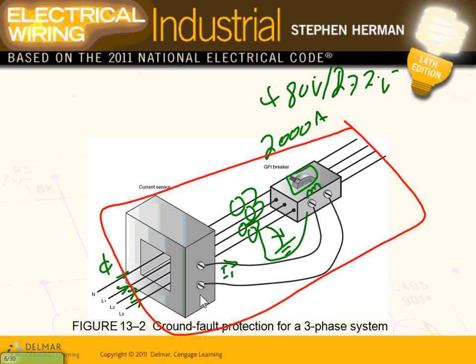So it senses what's going on in the ground and will alarm you. Why? Because a circuit breaker by itself cannot sense a ground fault fast enough. Take a ground fault on a 4,000 amp switchgear, which can be 200 amps. As far as the 4,000 amp circuit breaker, we're having fun here. We have 200 amps.